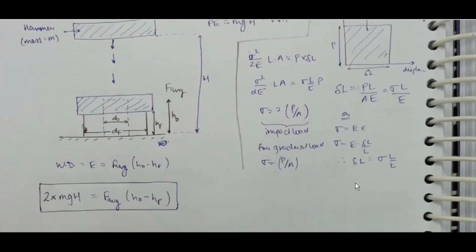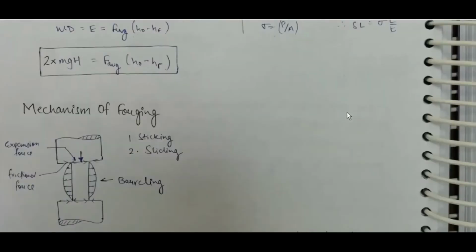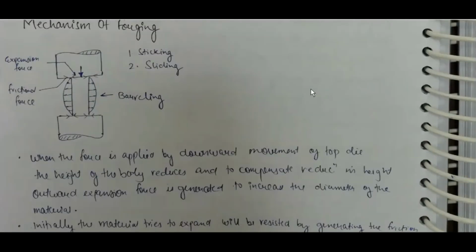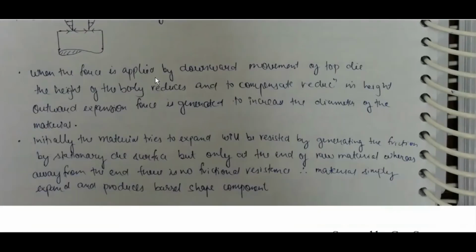Here the volume of raw material selected is 10 to 20% extra than the volume of the final finished component. The extra volume provided is collected at a place called a gutter. Because of the gutter, an extension gets produced on the forged component called flash. Flash is wastage which can be cut after forging by the trimming process. Final cross section: gutter, this is flash.